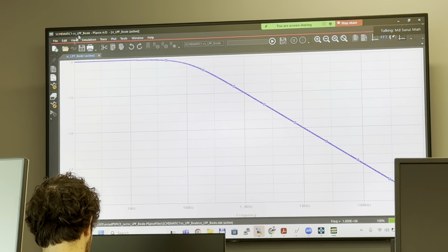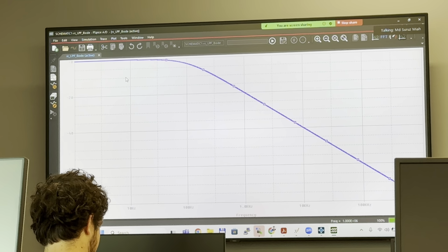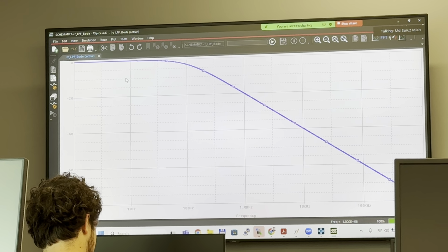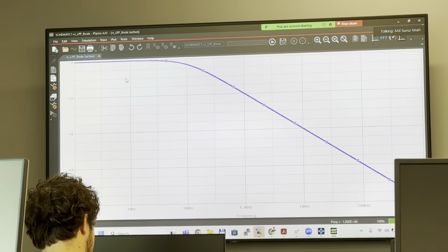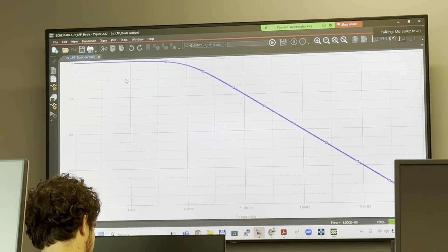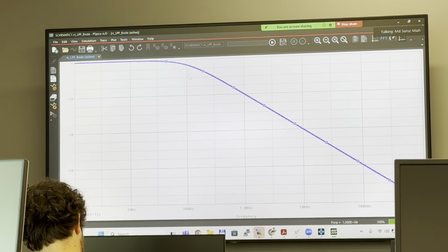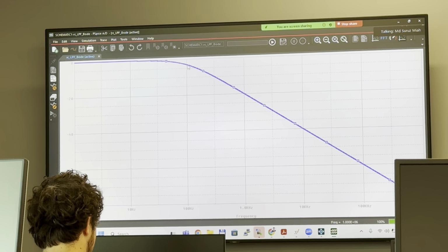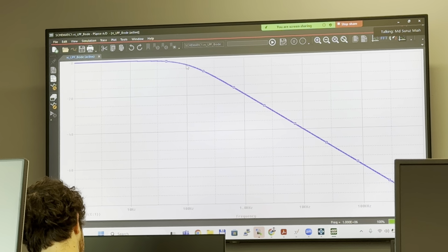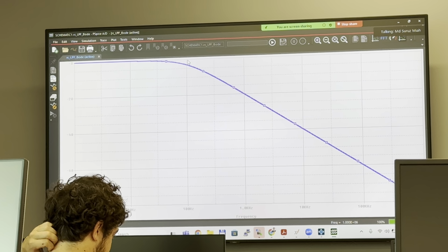So this is going to be in decibel. The break frequency is 1 over 2 pi RC. If you substitute the values of resistance and capacitance, you will see the break frequency is about 100 hertz. So at break frequency, you see this difference is about 3 dB. So it makes sense. All right. So that's all I'm expecting from you guys.